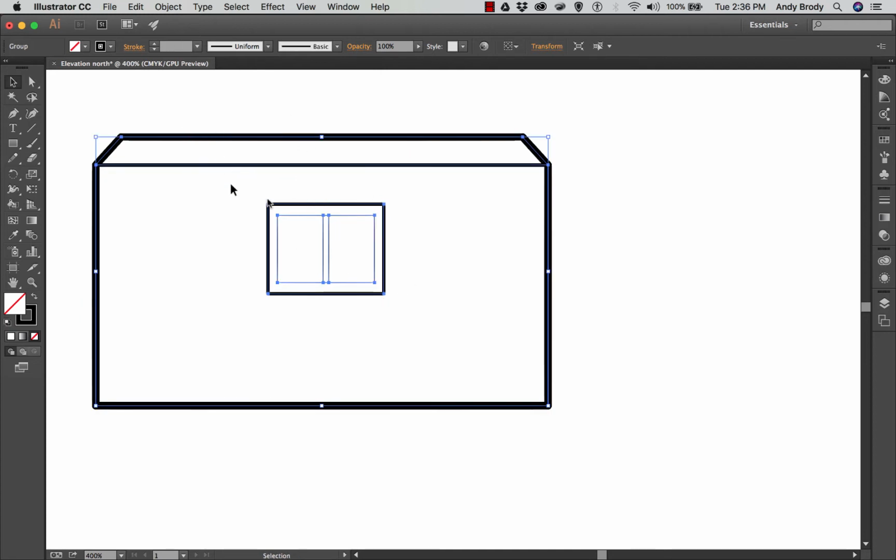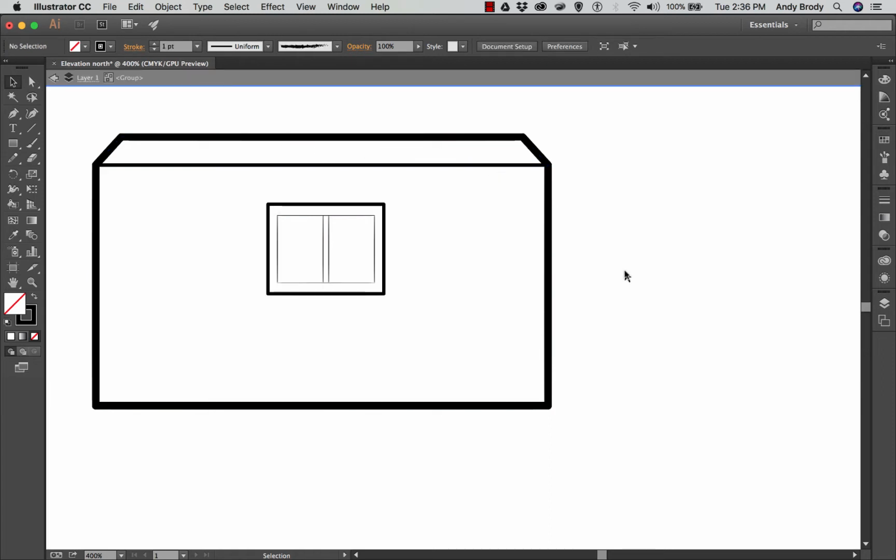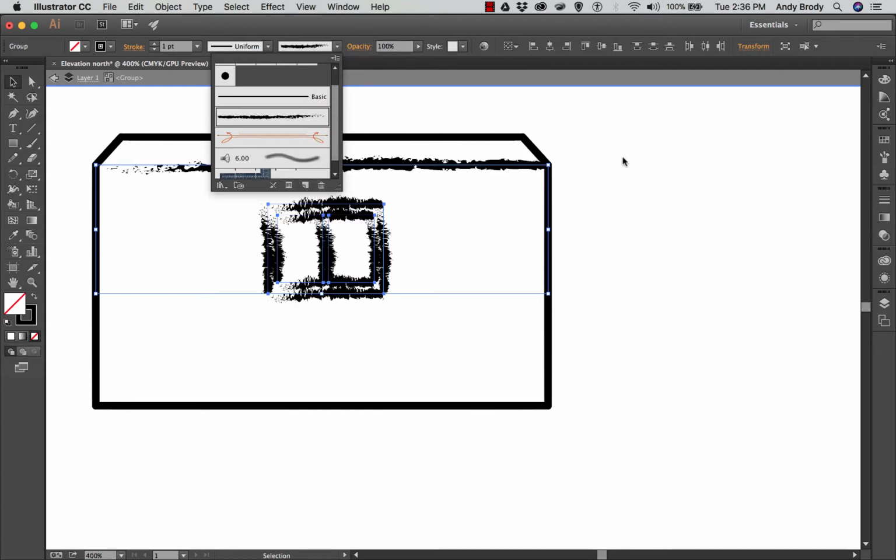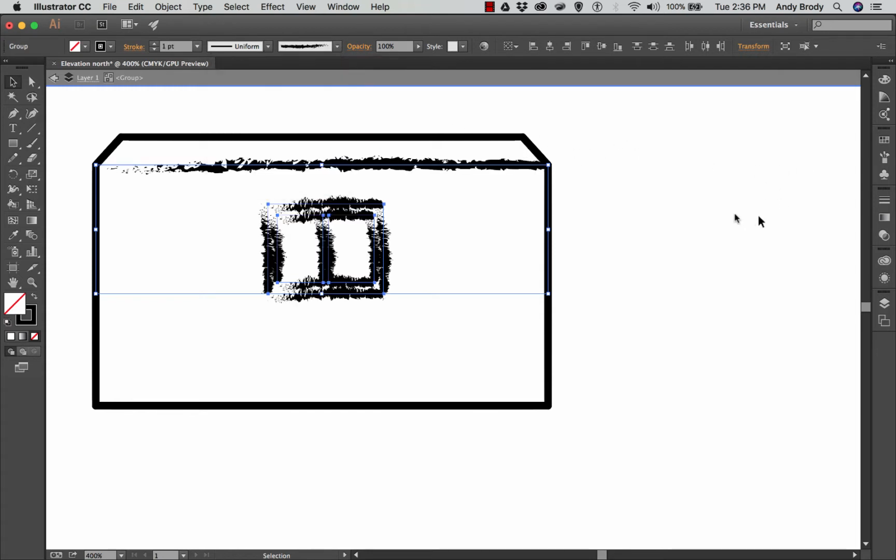I just want to change some of these interior lines. So if you double-click on the object, now I'm actually kind of inside it, kind of like editing a block. I can click and drag a window and select just these interior elements. And now I can change them to a different type of brush. But that's not really my favorite brush.